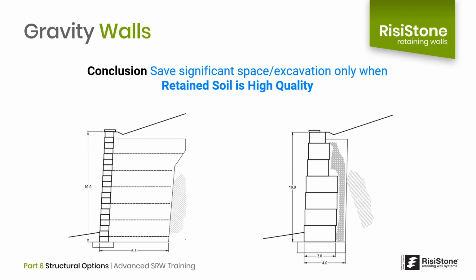So we can then draw the conclusion that gravity walls only save significant space when the retained soil is of very high quality. So when competing with large wet cast gravity walls on the market, we really have to question what assumptions are being made on the retained soil. If a preliminary design is used for a bid and it is conveniently assuming very high quality soil, but it is full of disclaimers, we need to question that.